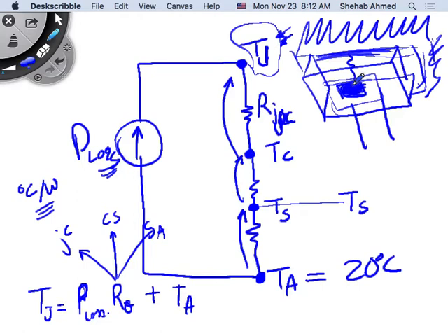And you cannot just put some grease and put it on a heatsink. You have to put electrically insulating, thermally conductive sheets, like a piece of paper. But it's a good thermal conductor and electrical isolator, right? So depending on